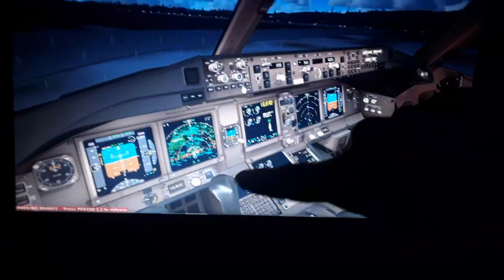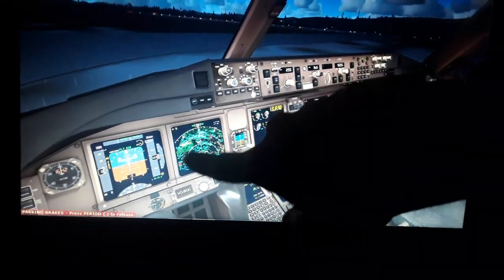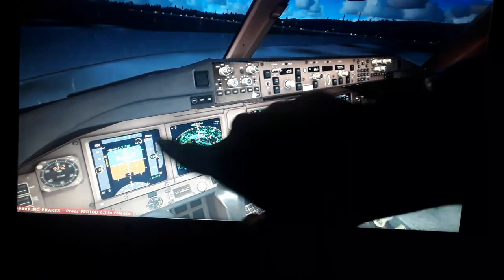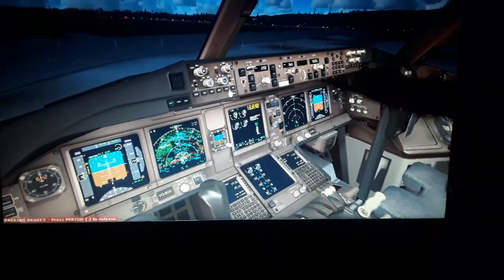So I'm going to show you how to do that. We're going to use the flight management computer here, and this is going to be displayed like a flight plan over here in the navigation display later. So you're going to see also the takeoff speeds. So I'm going to show you then. Also, we're going to make a complete flight path or flight plan for the route using the flight management computer route creator. We're going to insert the departure runway and airport, as I said. We're going to use the SIDs that are in the departure.